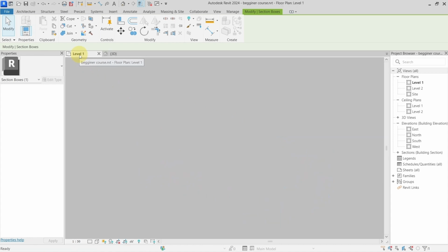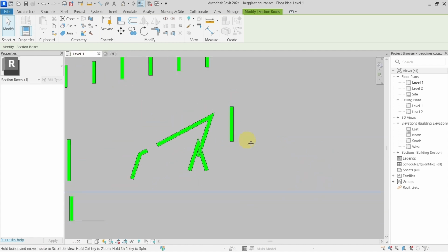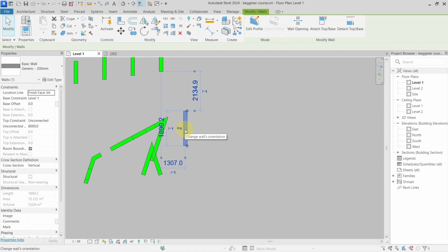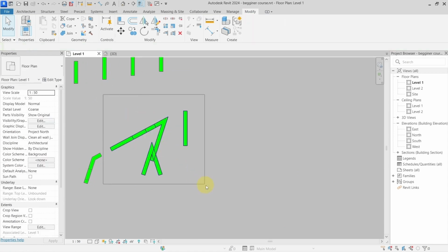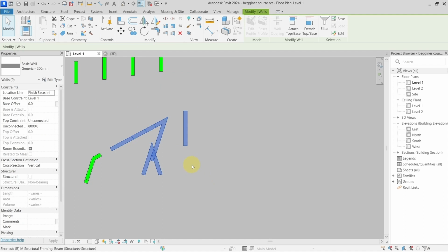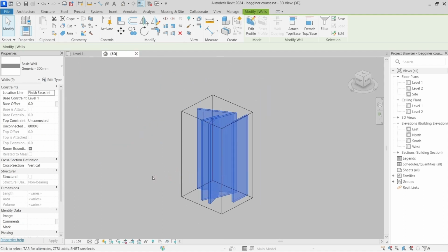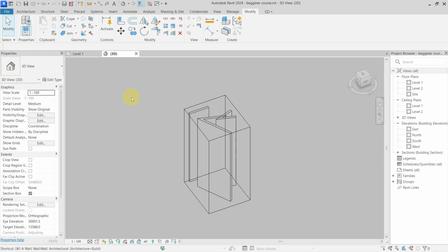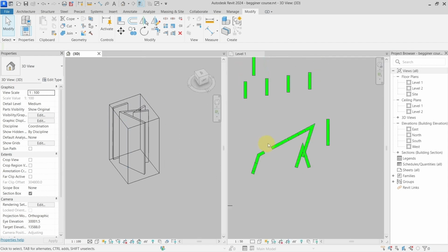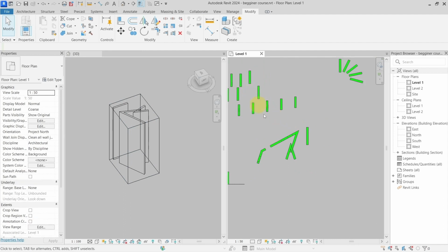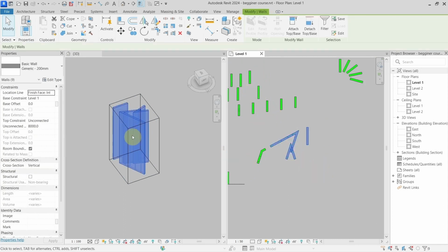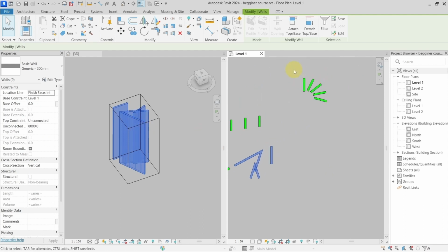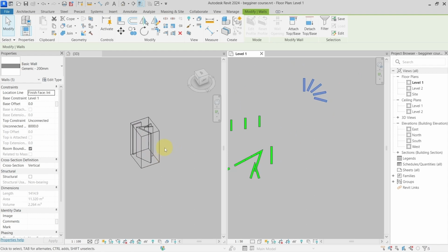And if I go back to my BX shortcut example, if I select this wall, or let's say that I select all of these walls and I press my BX shortcut, you can see that it opened the 3D view and it automatically created the section box around the selected elements. So if I place this side by side and do it again, now you can see that I have a section box around these elements. So let's say I will select those elements which I now cannot see in the 3D view because they are cut by the section box.